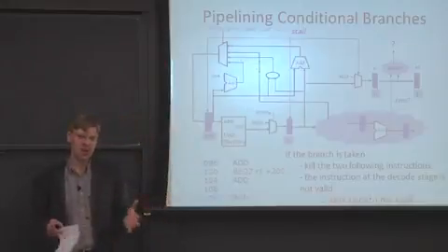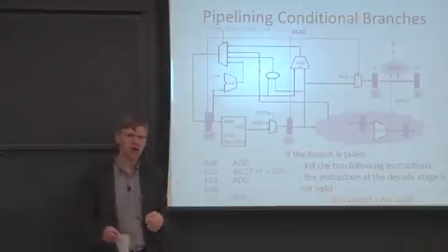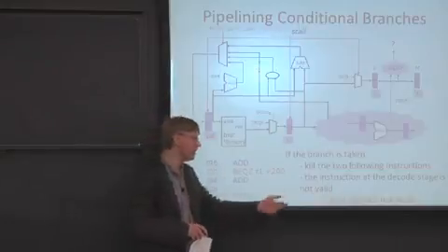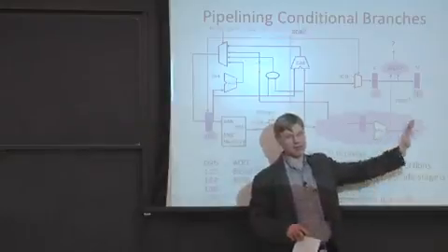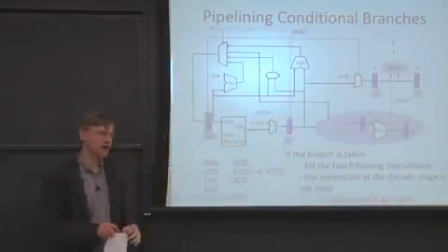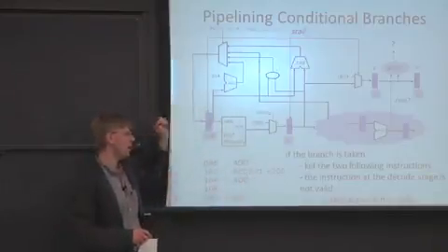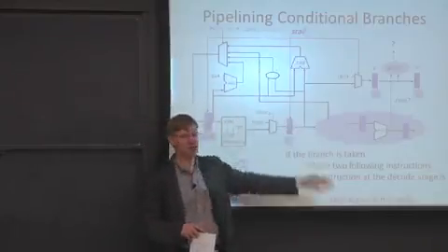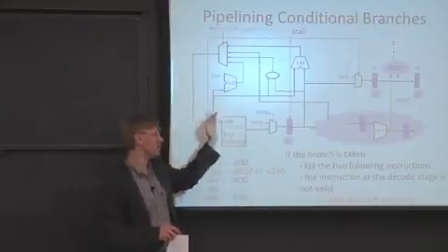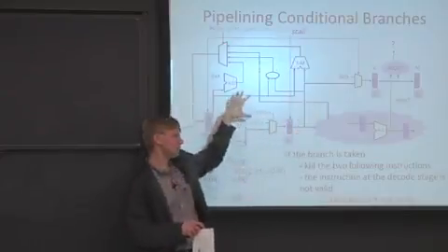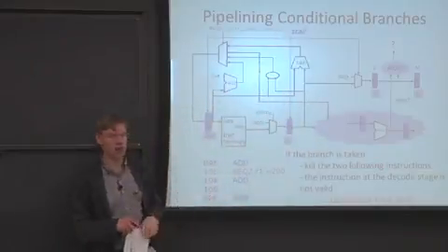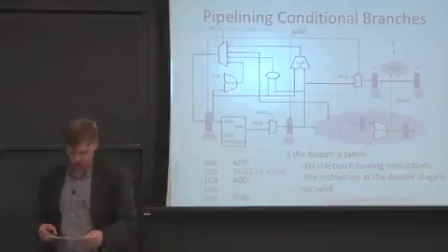So unlike the jump case where, well, you might be able to do either way with the priority of the stall and the kill wires, here the kill has to take precedence, or the redirect has to take precedence. And that's going to redirect the front of the pipe and basically clear out everything here. And if you were to stall it, you would not be clearing it out. So instead, you need to kill, sort of turn these all into no-ops, and redirect the front of the pipe to go fetch the actual target of your branch, of your conditional branch.